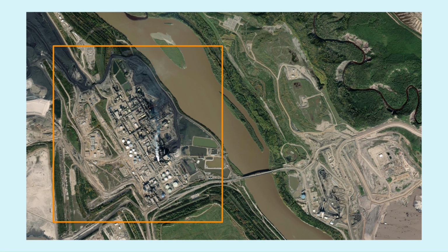In this case, it was oriented to fit the direction of the river. Its numbers are smaller. The false easting and false northing are in the tens of thousands, rather than with a UTM zone in this area, which has the northing in the millions and the false easting in the hundreds of thousands. With less digits, less likely you're going to make an error, easier calculations. And finally, a scale factor was chosen that fits the ground in this area. So what that means is a unit of measurement in the custom coordinate system or in the plant grid matches a unit of measurement on the ground. So essentially a foot in the grid is basically a foot on the ground.